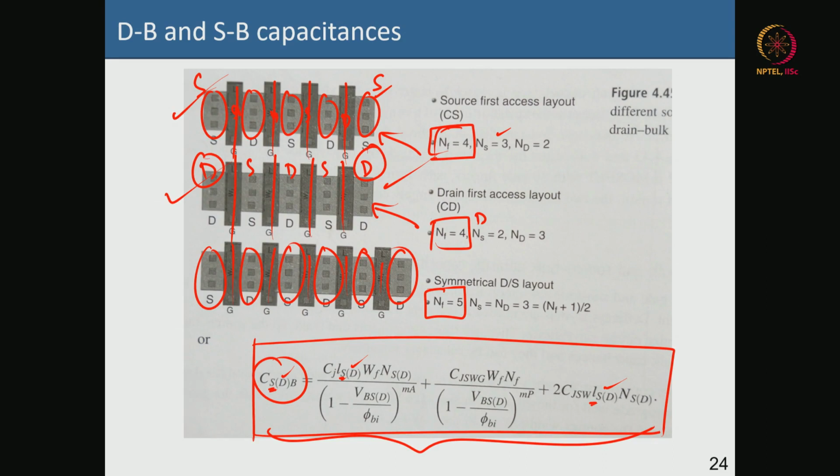The idea is that you want to minimize the capacitances without losing channel control, of course. So how do you bring down the parasitic resistances and capacitances as low as possible for high speed device applications, for a higher FT or Fmax, for better noise performance, etc.? With that we will come to a conclusion of this lecture.